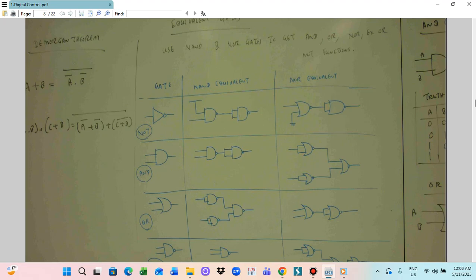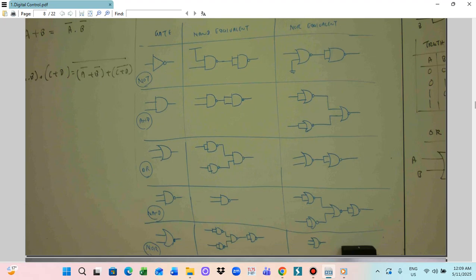So now I give you the equivalent gate table. The equivalent gate table means that if I have only NAND gates, or only NAND gates and NOR gates, and I want to construct a NOR gate, AND gate, OR gate, or XOR gate, I give you the equivalent combination of NAND gates to get the required function. Those functions are derived by applying Boolean algebra and the De Morgan theorem. We use the De Morgan theorem and the Boolean postulates. So those are the equations. This means that for the AND gate, OR gate, and NAND gate, the function can be written as a mathematical equation.